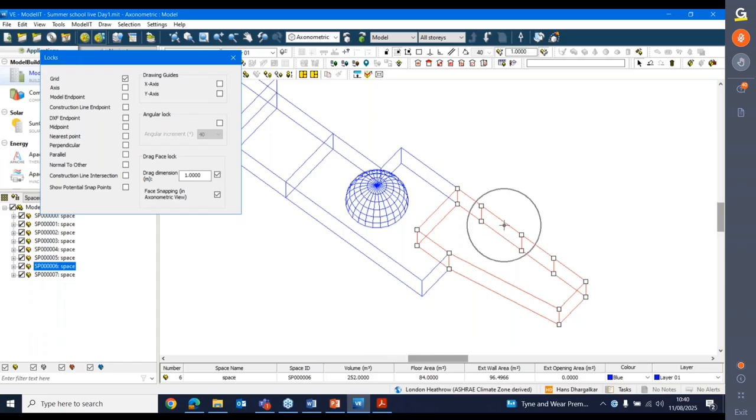If I deleted that wall, it wouldn't become a room anymore because it becomes external. If you want to model, say, a trickle vent or a louver, you could draw a very small door. I'm going to show you later on how to draw doors and windows. And then in our macroflow tool, which is our natural ventilation tool, which we're going to look at quickly tomorrow, you can open that louver or trickle vent permanently, and then you'll get airflow for that based on wind and buoyancy effects. So you can model external holes by modeling louvers as doors or windows.